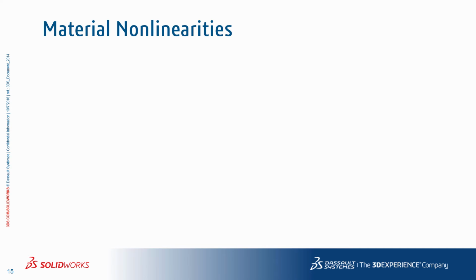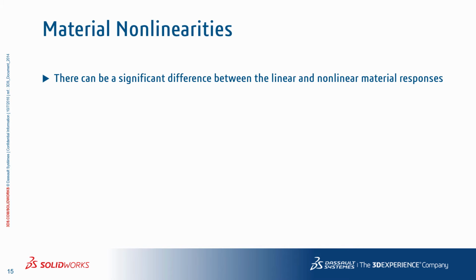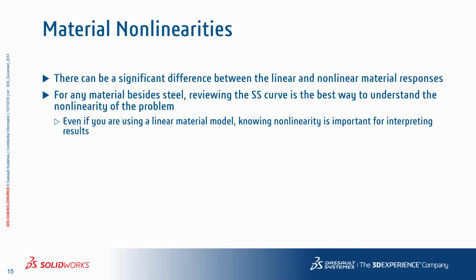To sum up the discussion on material nonlinearity, note that there can be significant differences between the results from a linear versus a nonlinear model. The higher the strain levels, more nonlinearity can be expected. For everything made out of steel, nonlinear modeling is pretty straightforward. However, for other materials, it is always recommended to get a copy of the stress strain curve and review it to get a feel for the nonlinearity.